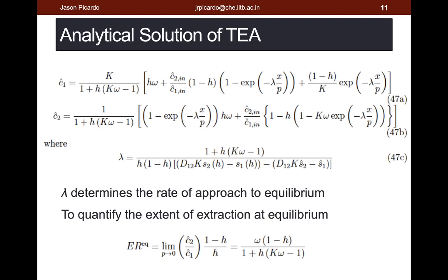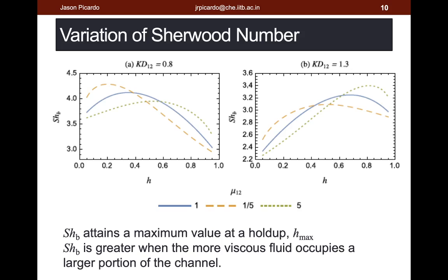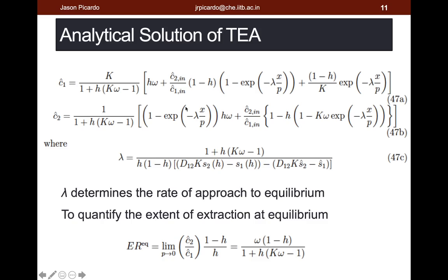Okay, and the last interesting thing is that the model, in the absence of a reaction with just mass transfer, can be solved analytically, and these are the analytical solutions. From the solutions I can identify this parameter lambda, which is locked inside this exponential decay of the concentration of C1 and exponential increase of the concentration of C2. In either case, lambda denotes a characteristic length. It tells me how quickly I am going to reach equilibrium along the length of the reactor. So the greater lambda, the faster I reach equilibrium in terms of residence time inside the reactor.